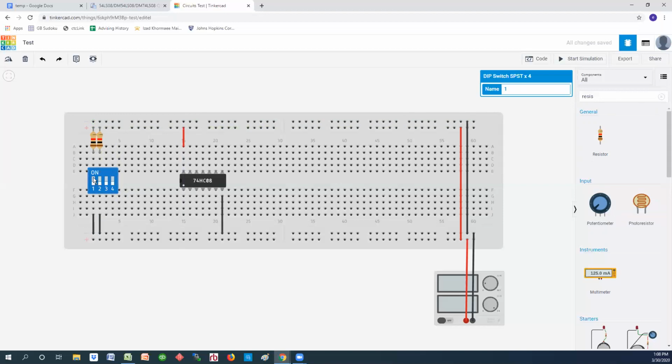When the switch is turned on, this switch is closed. On means closed, so it's connected to ground. And then when it's open, it's connected to a pull-up resistor. So when it's open you see a 1, and when it's in the on position, you'll see a 0 from here. But if you haven't studied, you've got to go back to the text and review that as well.